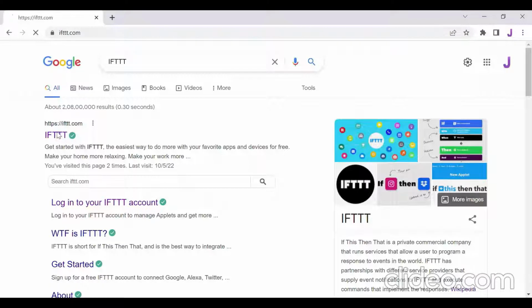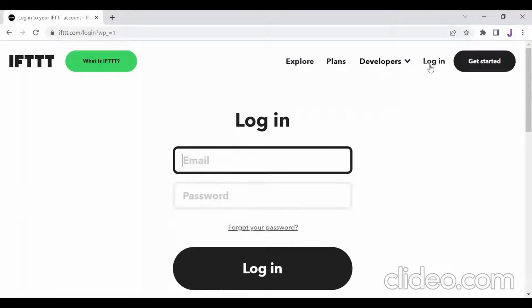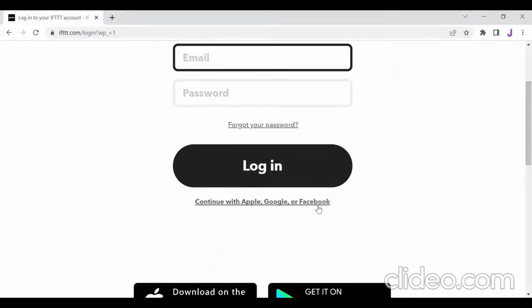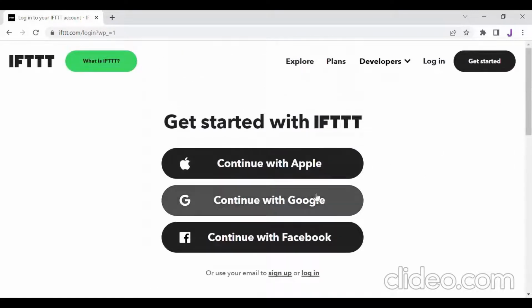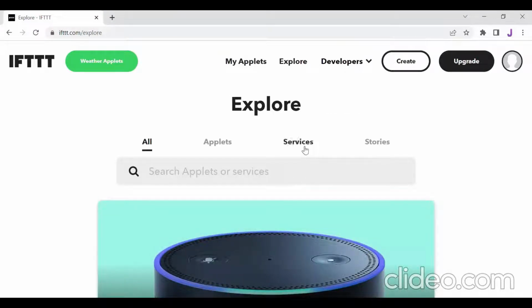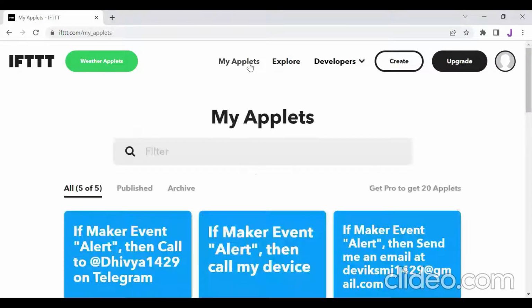There are many services provided by IFTTT. First of all, we have to sign up in IFTTT using either Google account or Facebook account. From those service provided, webhooks is used here to receive the web request sent by the ThingHTTP of the ThingSpeak. Webhooks connects the external web applications to IFTTT, and so it reacts to ThingSpeak data. Then, if webhooks have received the web request, it does the actions given by the user. Both the webhooks and the actions provided are saved as an applet in IFTTT.